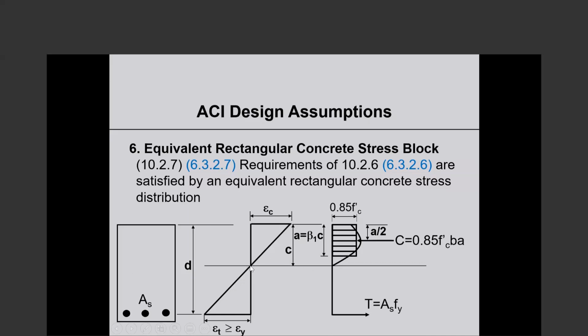He took a stress distribution which was the reverse, highest at the neutral axis, going down to zero at the extreme compression fiber. It was obviously an absurd stress distribution. And he showed that even that absurd stress distribution gave him nominal strength in substantial agreement with test results.